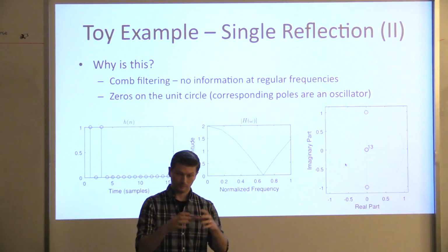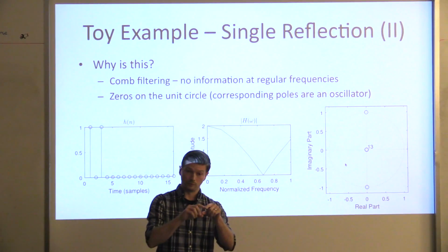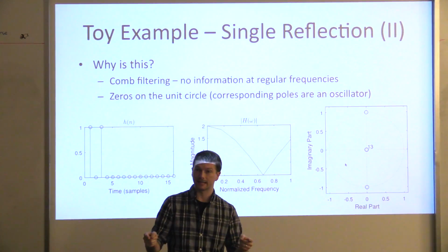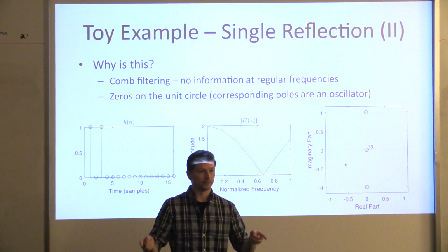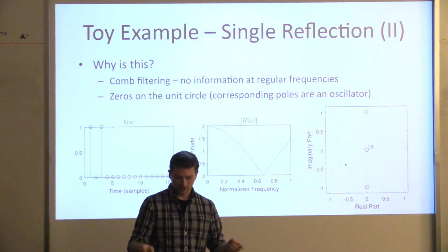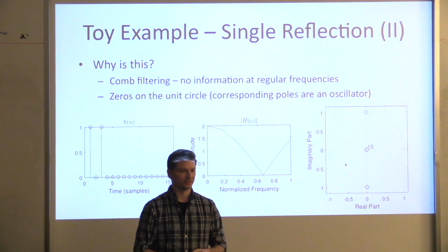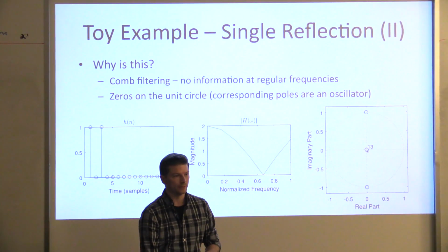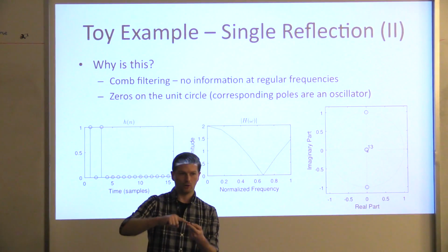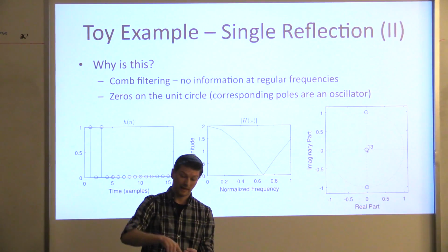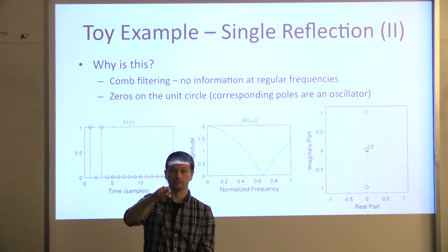Another way of looking at it, as Malcolm pointed out, is that you take the Z-transform. So you treat it as a Z-transform, you factorize it. So we've got 16 taps here, most of which are 0. You're going to end up with 15 factors, 13 of which are just going to end up at the origin and don't really do anything, but 2 of them are going to end up on the unit circle. They just so happen to be lying on the imaginary axis.